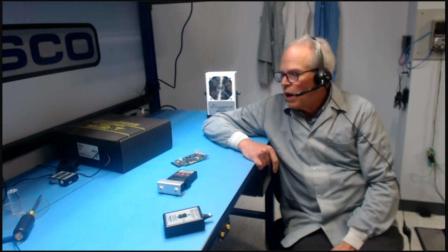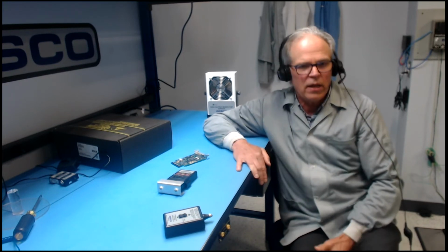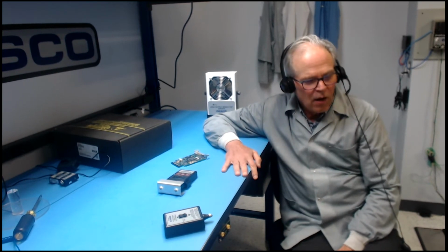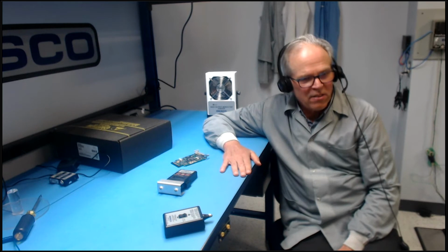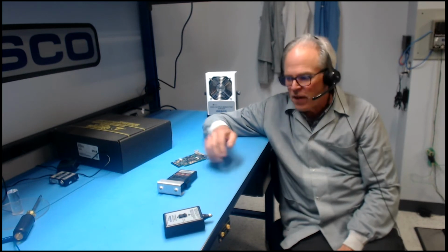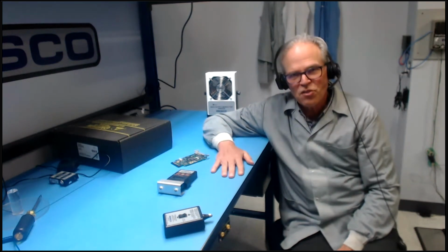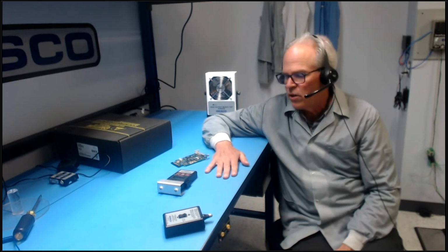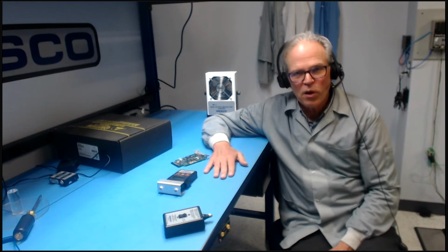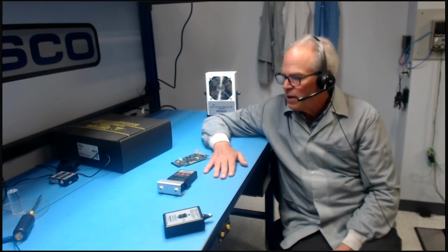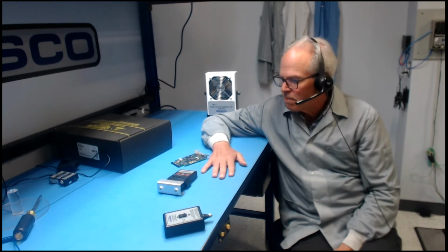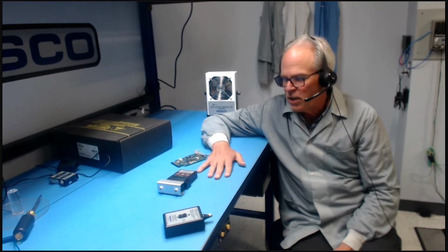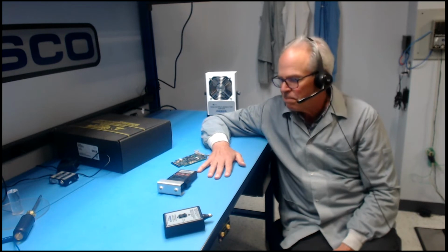Okay, so there was a lot there. We're going to be sending you the video of it. In closing, if I had to make one suggestion to pay attention to, it is to figure out how fast your ionizer has to work, so you don't set a requirement that can't be met, or maybe not meet the requirements that should be met. But proper testing and proper identification of the speed you need is what's important.